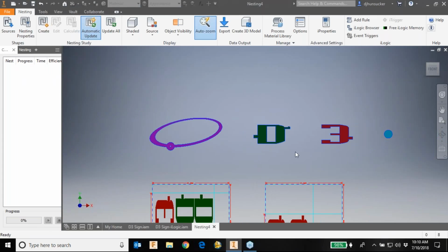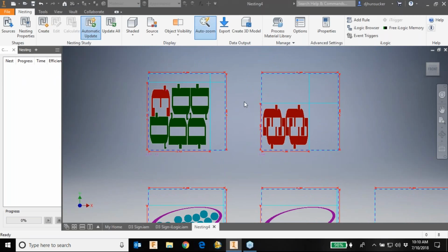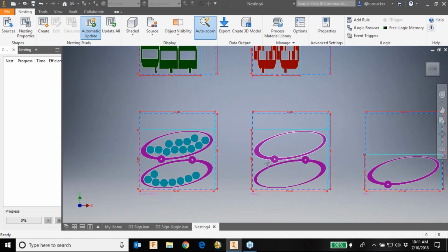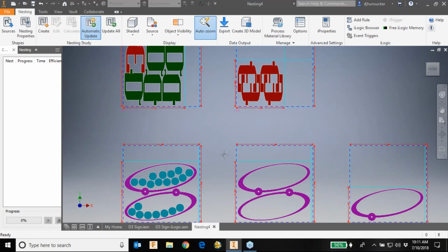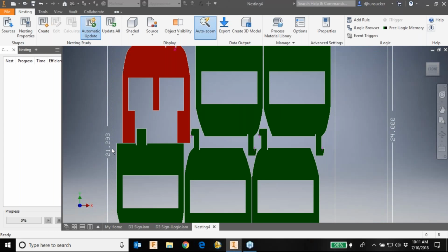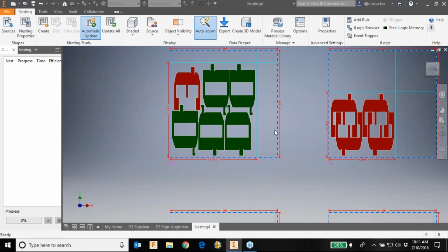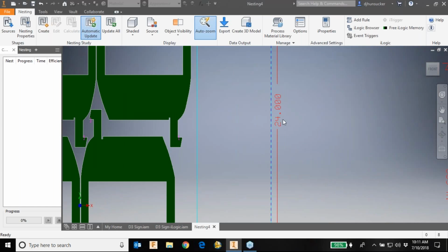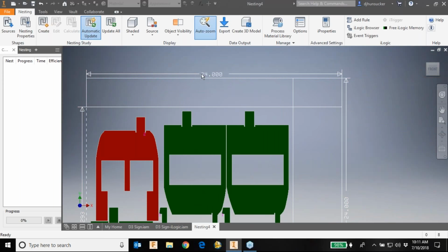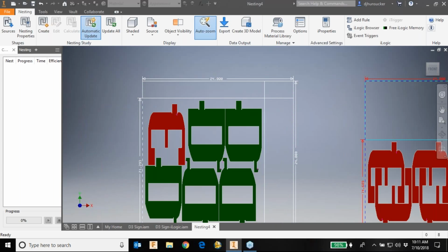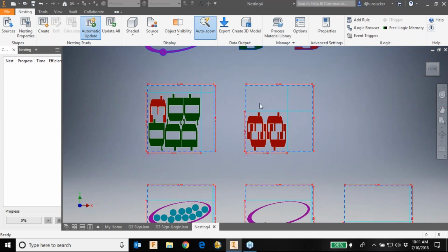And what you'll see is, down below, it says, okay, to create 5 of these, it came out here and said, well, here's a couple of these, here's the other material thickness in there. Now, it shows me how it fitted in here, so at 21.2, 19, and it also came out and said, well, I'm using a 24 by 24 blank. So that is controllable. Right now, I left the default at 24 by 24 in here for it to use.